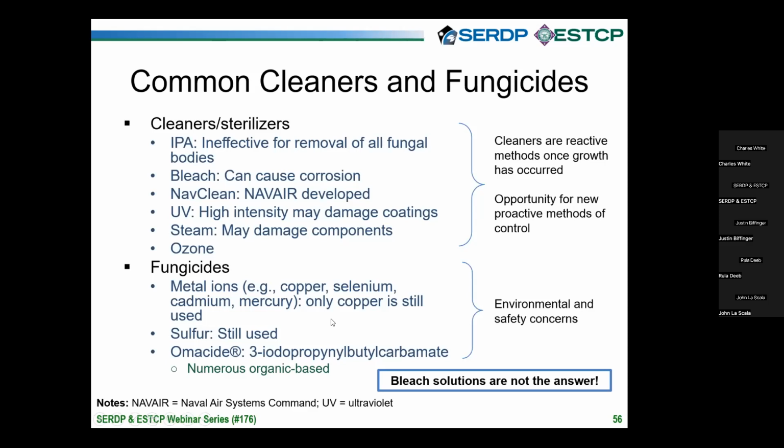The last takeaway I want from this slide is highlighted here at the bottom. Bleach solutions are not the answer. By and large, this has been the most common answer to our surveys for standard operating procedures, or what is available to ship's force to use. The bleach solutions are again very good at cleaning the macro growth, but will spread and exacerbate growth unless a certain concentration with a certain residence time is reached and can clean the hyphae from the surface.